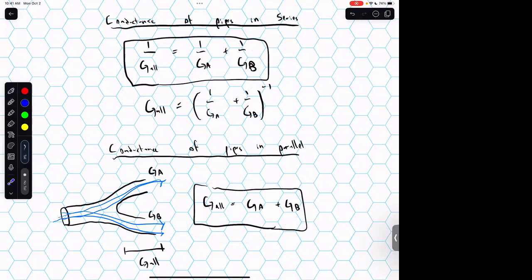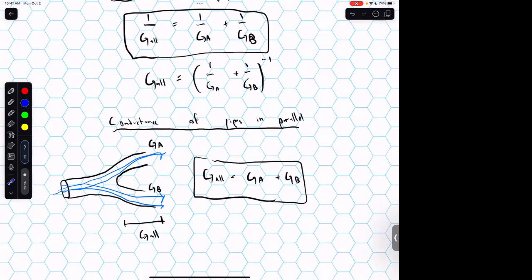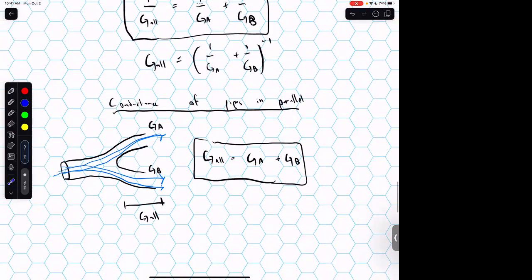Okay, so the reason that I really like talking about the conductance so much is because the conductance ends up being how we estimate how much energy overall is dissipated while I'm trying to pump my oil through some pipeline or something like that. So we can use the idea of the conductance to motivate finding the power dissipation of a pipe flow.